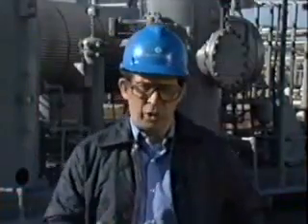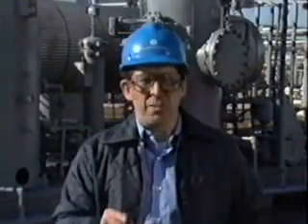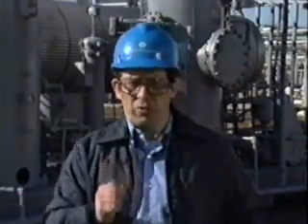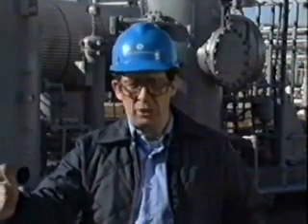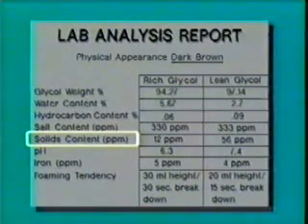Salt usually travels in the gas stream in a fine mist. Now, if the gas stream contains excessive salt, a coalescing or filter-type separator can be used to remove salt from the gas upstream of the dehydration unit. Solids content refers to the amount of suspended solids in the glycol. Suspended solids should be kept below 0.01% by weight using filtration.